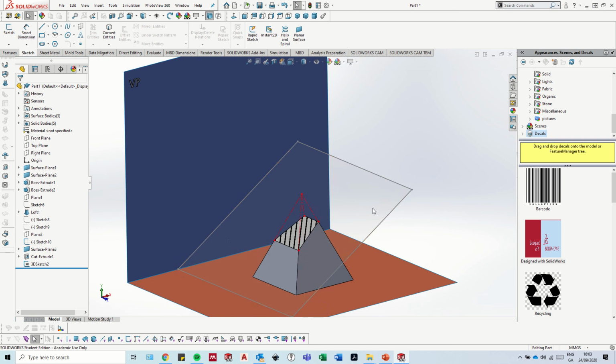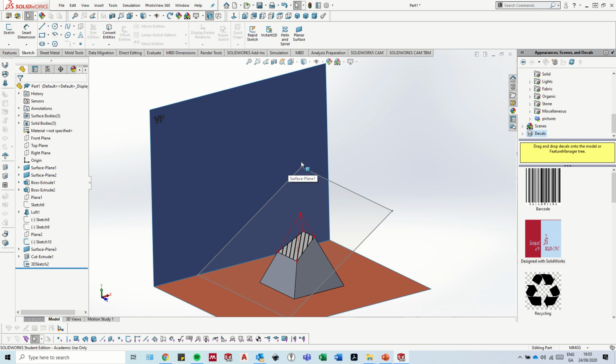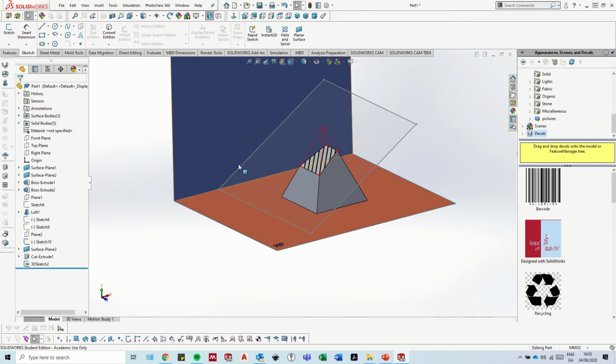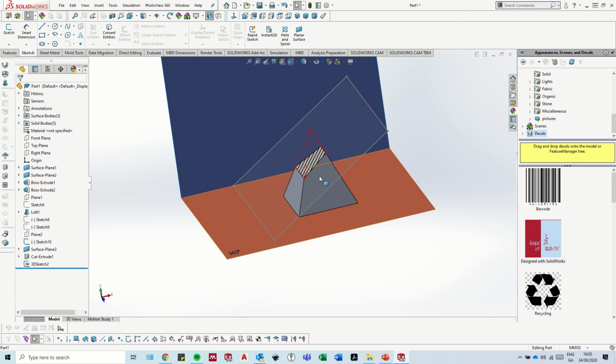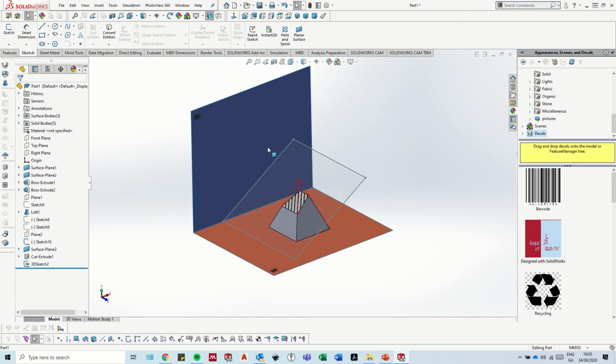Okay, when you're this far, all you really have to do then is indicate your different points. So for instance, again, just draw a line here and indicate using that text, using a center line and text. Put in here your V, put in here your T, and put below here your H. So for your horizontal trace, your vertical trace. Okay, and if you want, you can put your X and Y for the XY line below here. But after you've that completed, you can save this and submit it as your finished task.